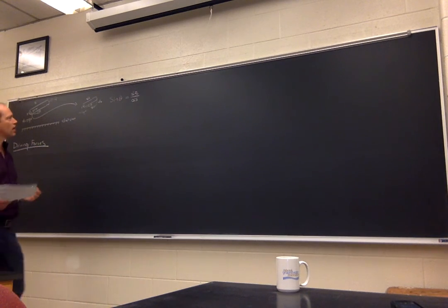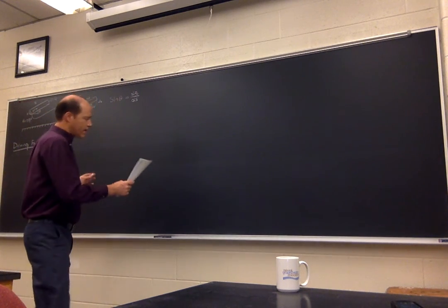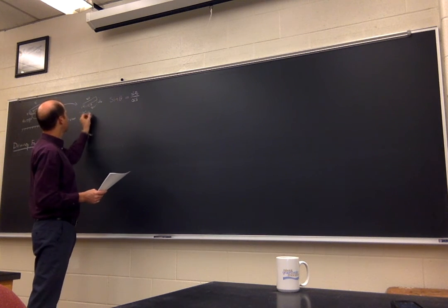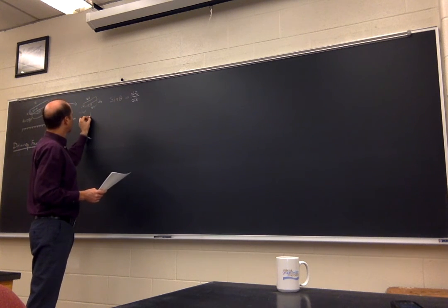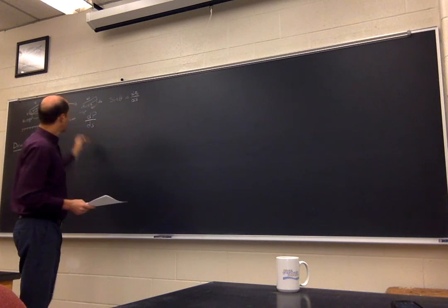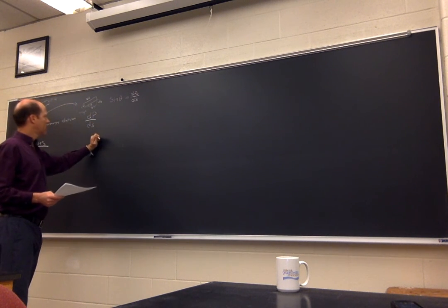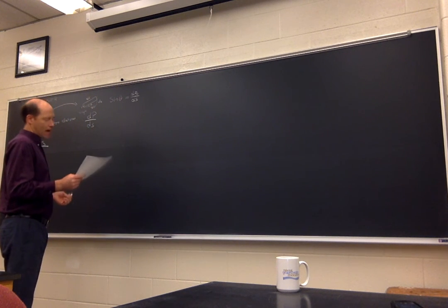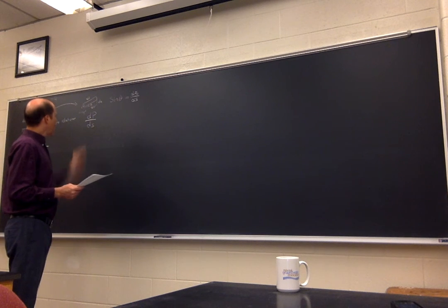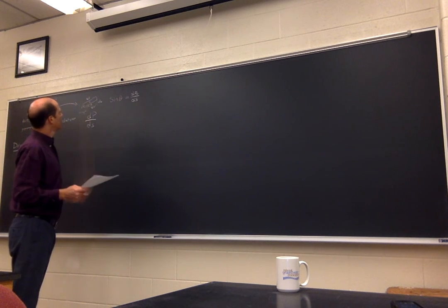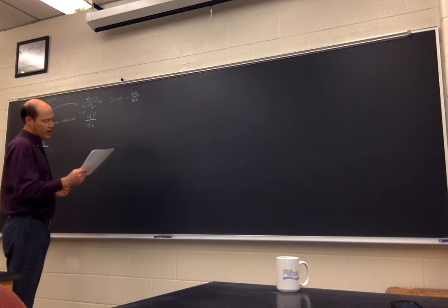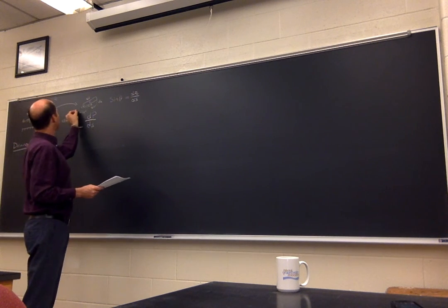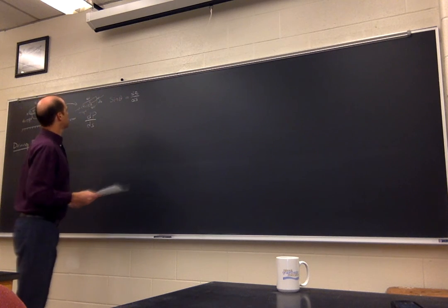So the driving forces of this problem are given by some pressure gradient that is acting on this, and that pressure gradient across ds is dP over ds. That is the pressure that is acting from one end to the other, the pressure gradient on that control volume. And so if we pick a centroid to that control volume, then we can assess the pressure that is acting on each side of this.